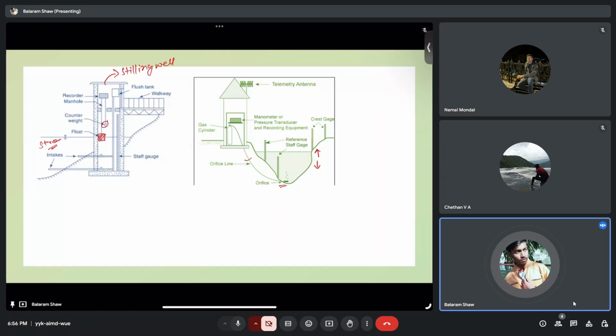If you see this, here we have several points, and from there we can create one rating curve like this. This is crucial because it allows the use of stream gauge, which is easily determined, as we just mentioned. I hope till this it is clear. We'll see if we have some questions on this.